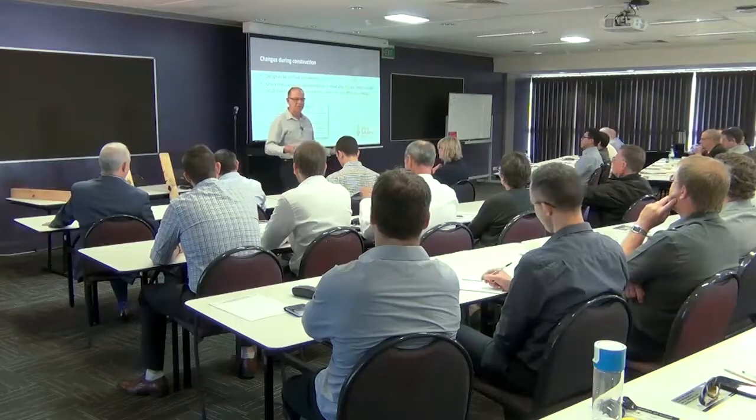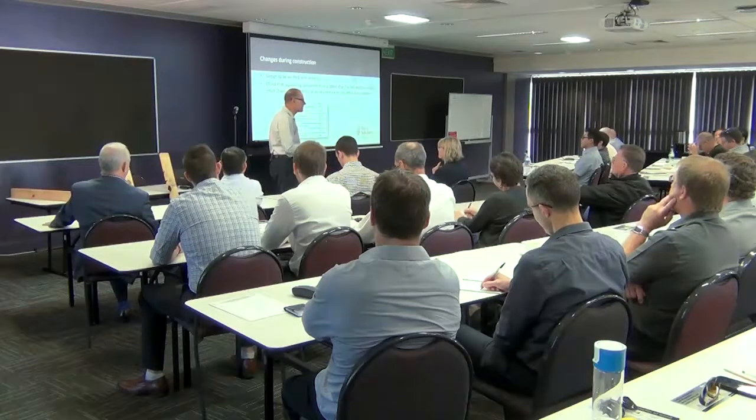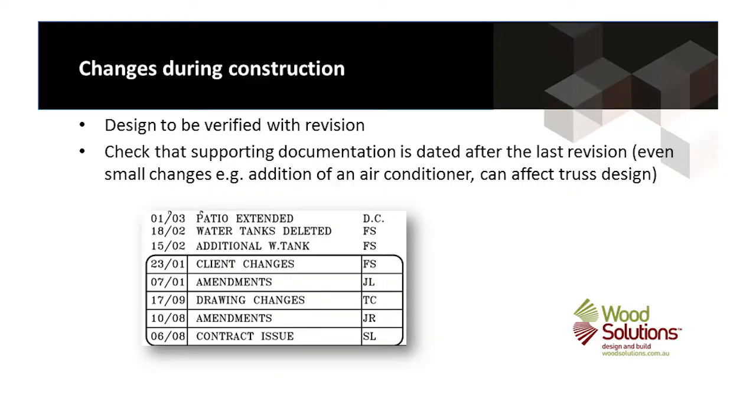Okay, often changes happen. Can you believe that? That as a building is built, some stuff gets changed. Make sure the plans and specifications are updated and shown on the drawings. And we'll look at some particularly important plans later on.